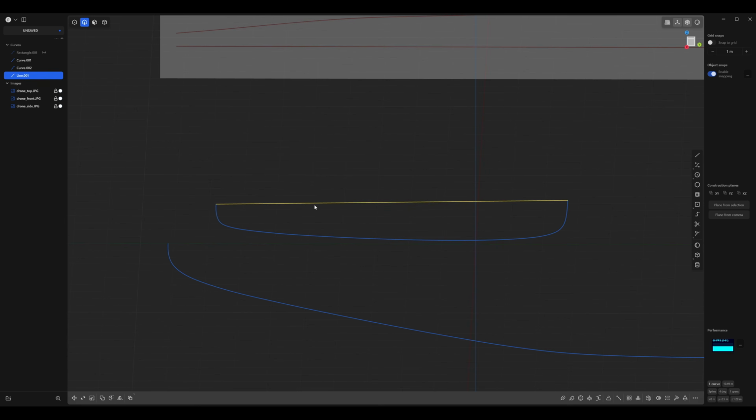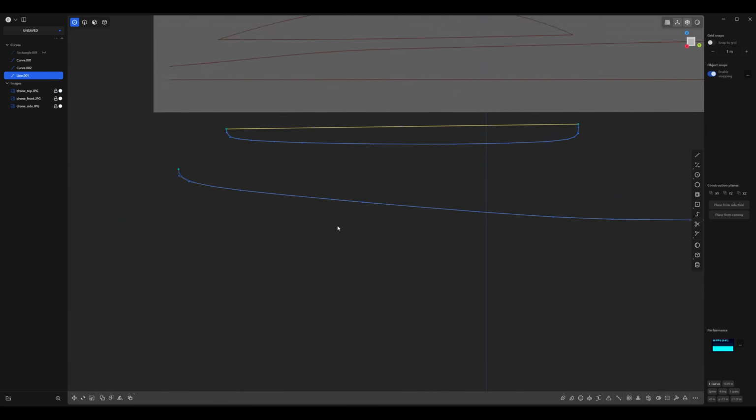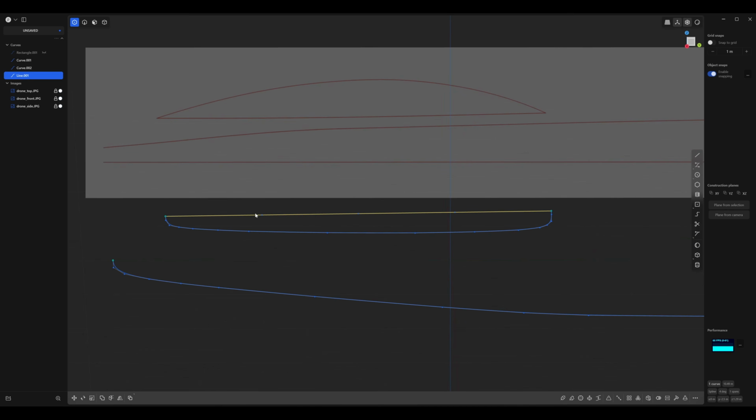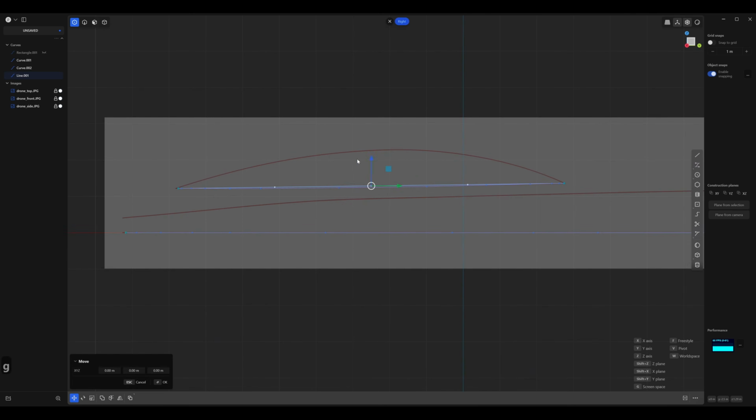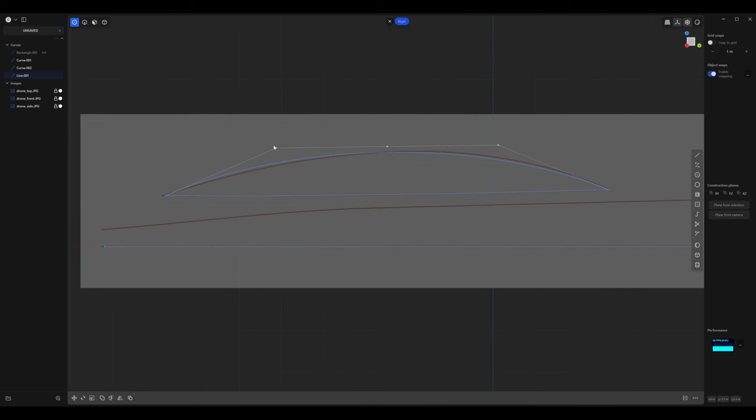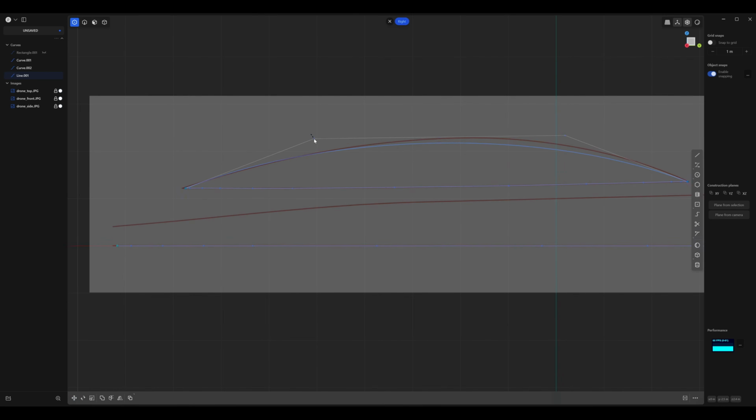When you click on it, you press 1, you can see there's 1 degree, 2, 3, and 4. And it also says that here, which just means that there's more points on the surface. And when you press 1, you can edit these points. So I'm just going to select all of them, go to the right view, press G, and move them upwards. And now I'm just going to adjust it so it matches the reference.